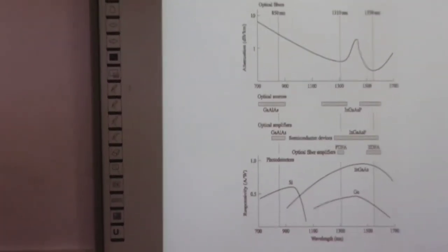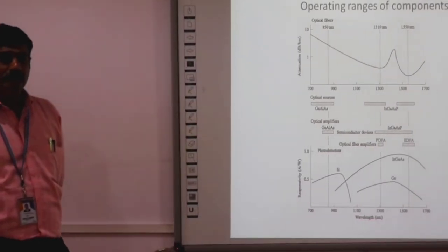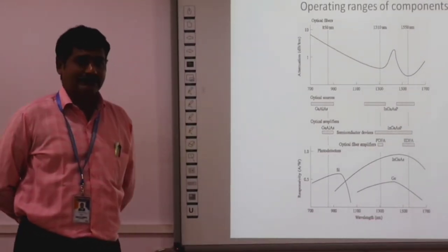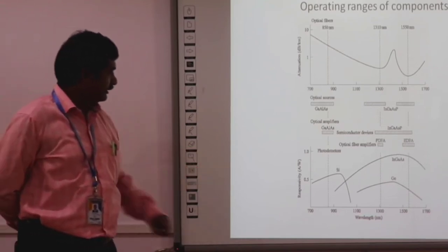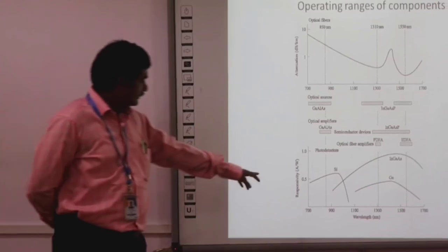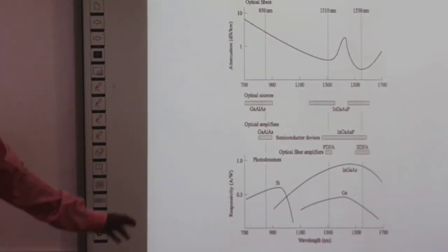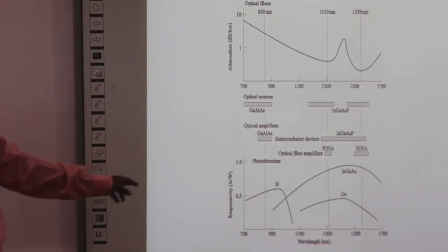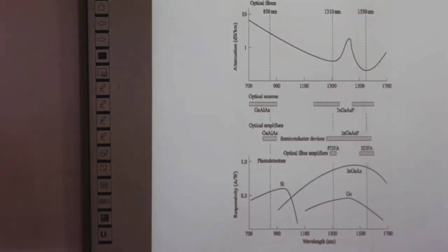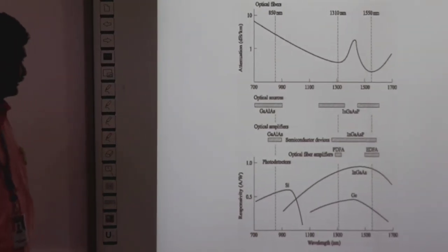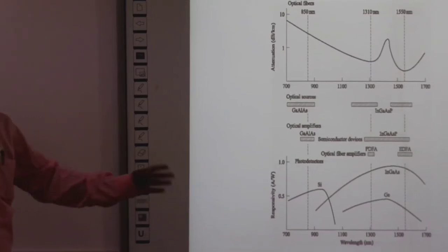So the three main elements of fiber optic communication are fiber optic sources, fiber and photodetector. In this graph you are seeing the fiber optic photodetector characteristics. For particular wavelengths, the responsivity, the performance measure of the photodetector, is also an important thing. The responsivity should be very high.